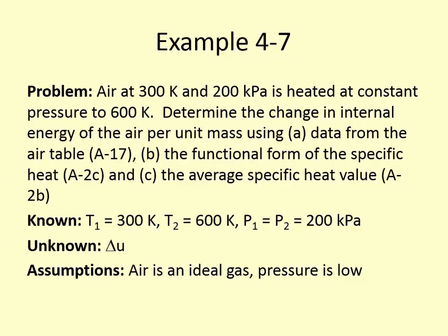Now this breaks down, let's say instead of going from 300 to 600 Kelvin, I was going from like 200 Kelvin to 2400 Kelvin. Okay, that's a much larger temperature interval. So making the approximation that the specific heat is some average value over that range is not as accurate. But for 200-300 degrees, it's pretty good. And it's a lot easier to do. It saves you a lot of time. Because if you want to know exactly what's going on in your system, the models break down anyway. You usually have to measure exact values. So that's that. Any other questions on this?